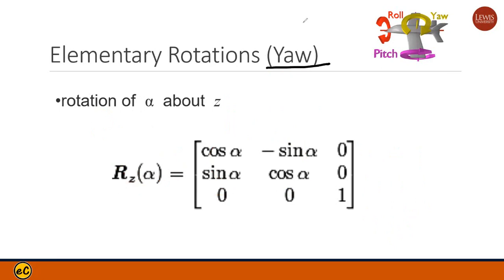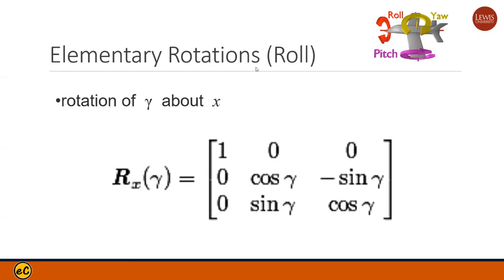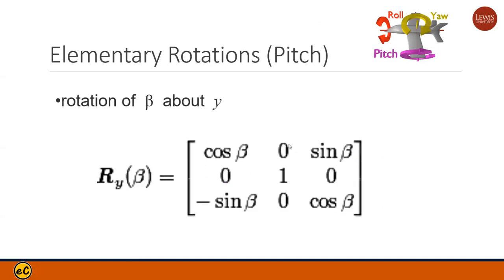So similarly, your rotational matrix for the airplane in beta. For this one, beta angle, your Y has no change. Your X and Z change, okay? And the next one, you do have the X axis roll. Your X has no change, your Y and Z change, okay? So you can see the 3D operation is based on the 2D rotational matrix.